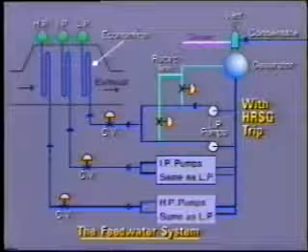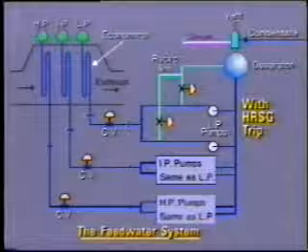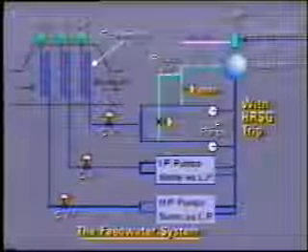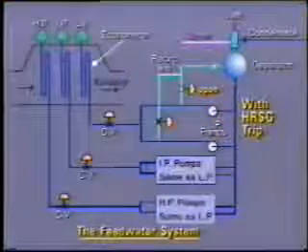When the condensate and feed flow reduces close to zero, the respective recirculation valves will open so as to maintain minimum flow through the pumps. The pumps themselves would only trip out on loss of suction pressure or an electrical fault in the driving motor.